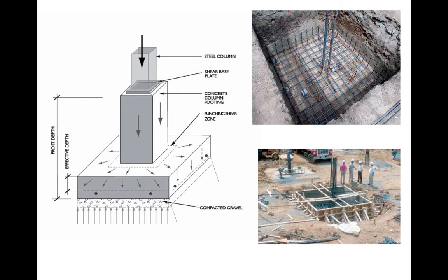The way these work is that we always transform from steel, if we're using steel, into concrete. If the building structure is concrete anyway, then the concrete column can just come straight down through the ground. The steel column, of course, is vulnerable to corrosion and oxidation. So we try always to have at least a couple of inches of concrete above the soil level.